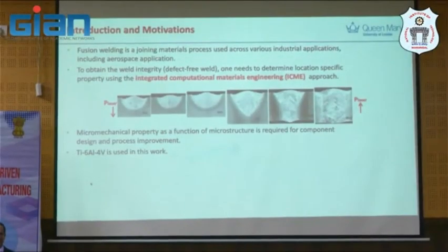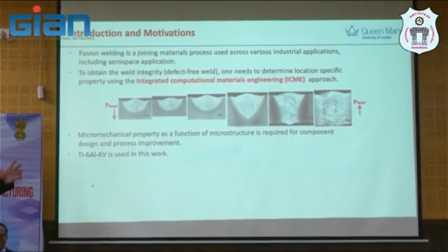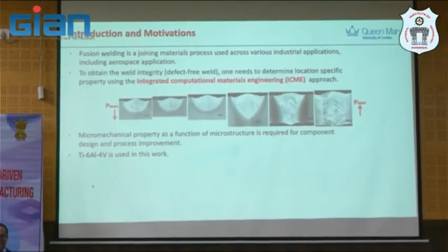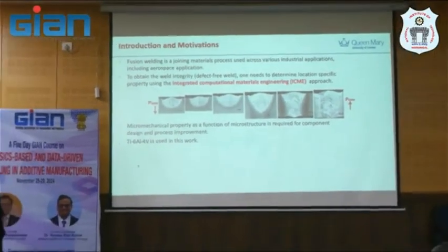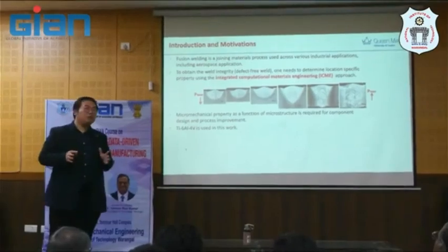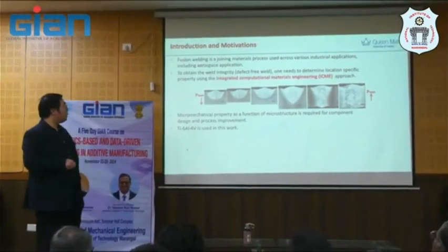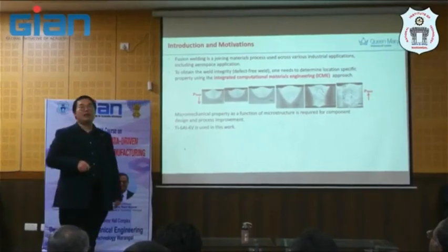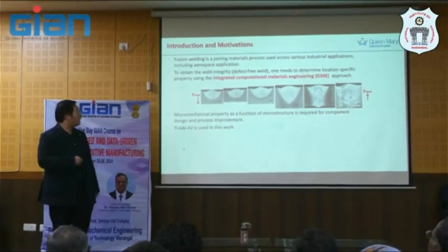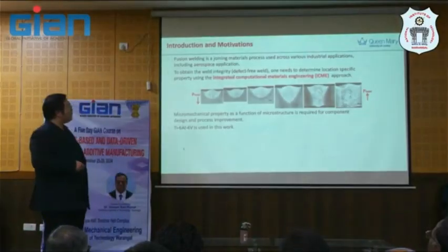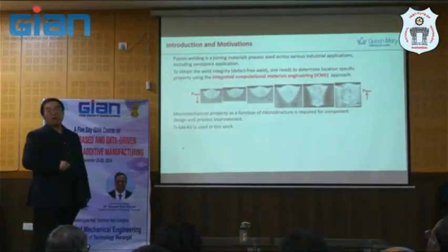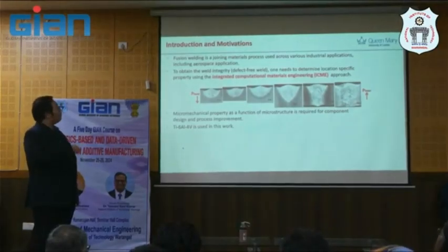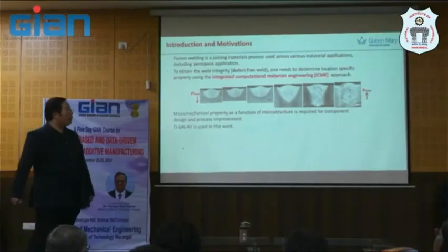But to obtain the weld integrity, or the structural integrity, which means a defect-free weld, we need to determine the location-specific property. And the approach we are going to use is the integrated computational engineering approach. I gave you the result before talking to you, but this is what we've seen from experiment when we vary the laser power, for example, in this case, and it changed the mode from conduction to keyhole mode.